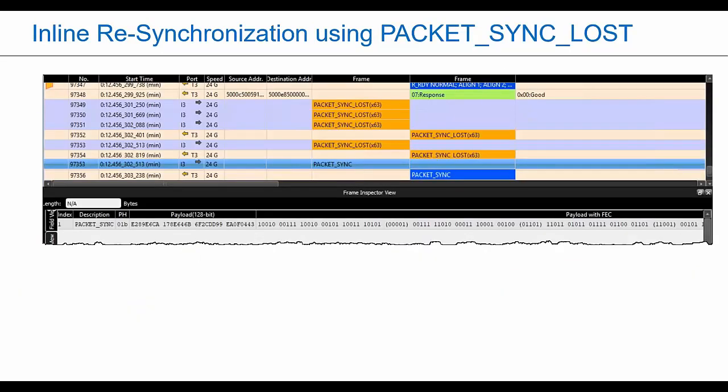A small side note, this same basic primitive handshake can be used to resynchronize the link in band without doing a full PHY reset. So this is a new behavior. Either side can initiate it, but probably it would first need to detect some kind of receive error or comma detect error.